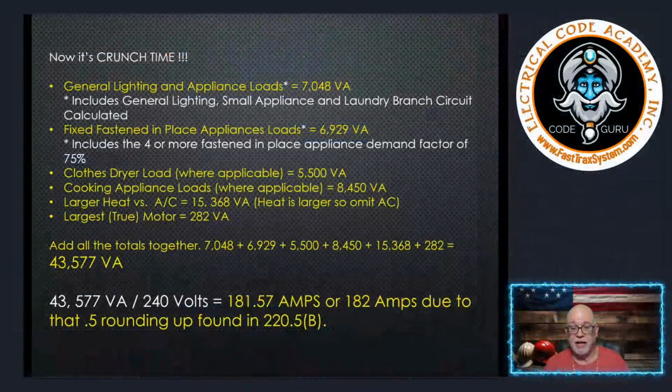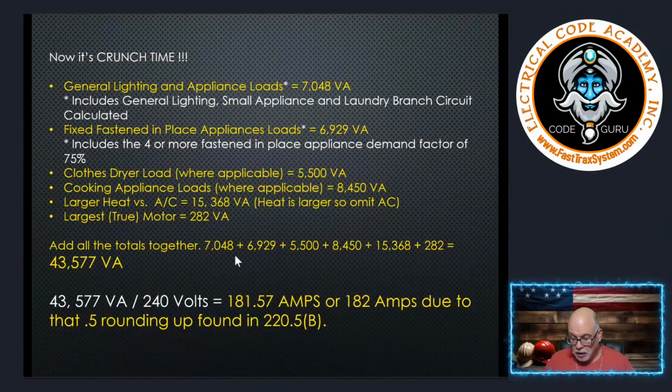Okay, so here we've got to focus. You could go running over to 310.16, folks, and simply go to the 75-degree column because of terminal limitations and temperature limitations of 110.14(C) and say, okay, I'm just going to find a conductor that can handle 182 amps and be done with it. But there's something you've got to remember. This is not an exception.